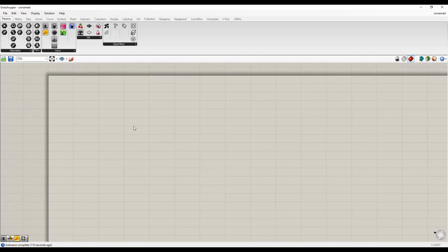So first is in Grasshopper, you do not create models, you only create algorithms. To create any action in Grasshopper, you access something called a component. To create a component, that is to do any action, double click with your left mouse button, and it opens up a dialog box like this. You just need to type the component's name. Component is an alternative to commands you have in a software that helps you to model. In Grasshopper, the alternative is called a component.